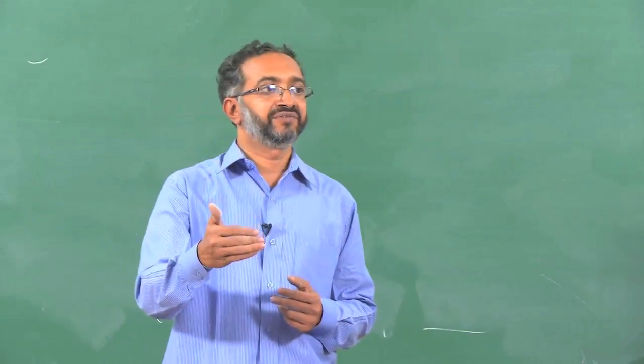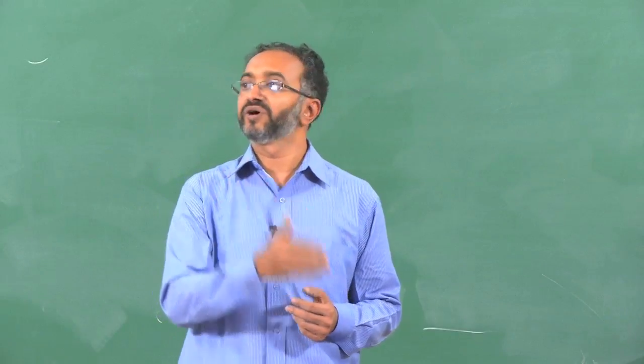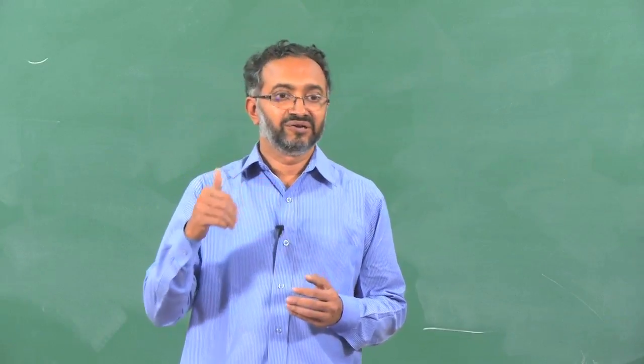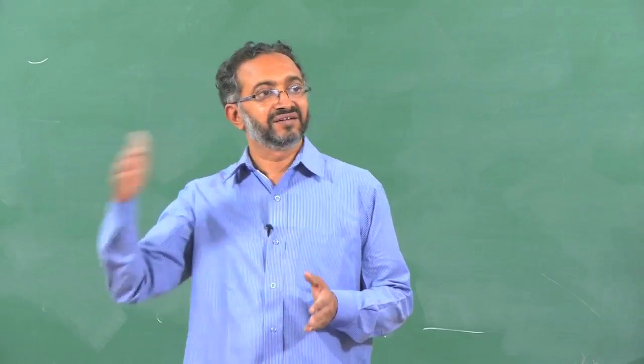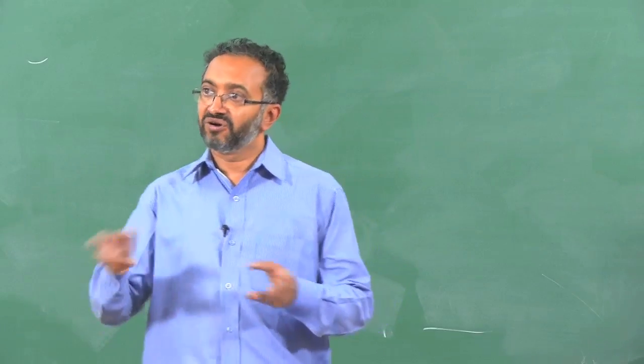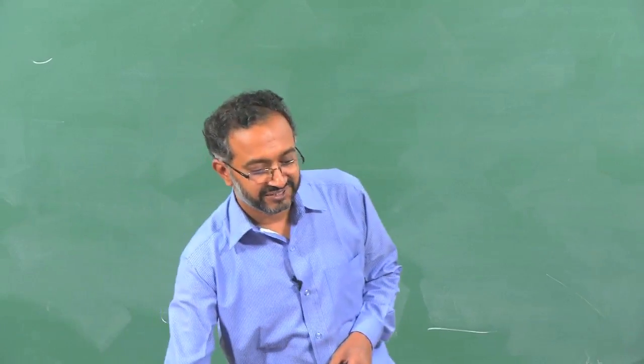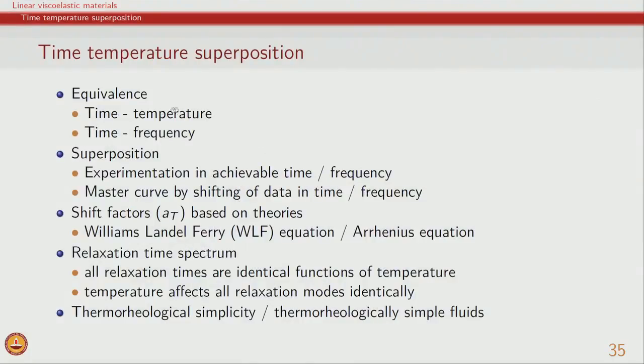Higher temperature behavior is like lower time behavior, lower temperature behavior is like larger time behavior. Conversely, time and frequency are related and therefore frequency and temperature are also related. Low frequency is analogous to higher temperature, high frequency is analogous to lower temperature.